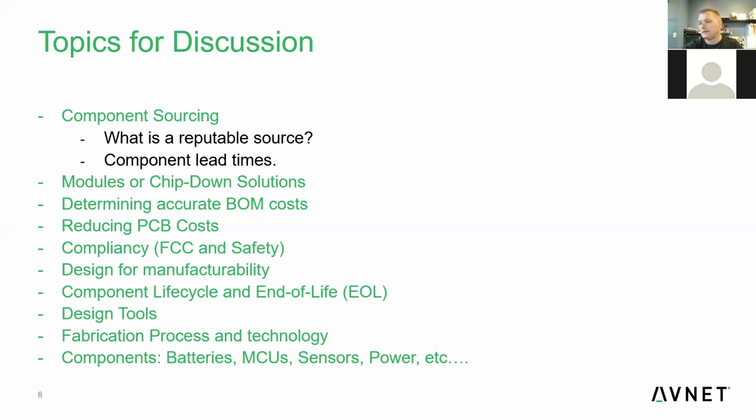It's really a couple things. One thing that I look for as we start to move into production, and when I start looking at some of your guys' BOMs, is I'm looking to make sure that the components you're using are not some obscure component that I feel nobody else is using, or made by one manufacturer over in Taiwan. It's important to avoid those things as much as possible. So, things that are single source.